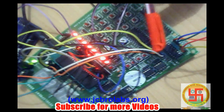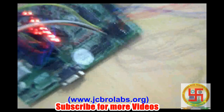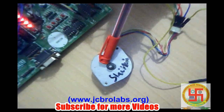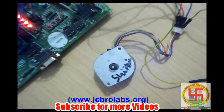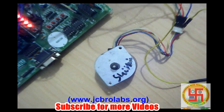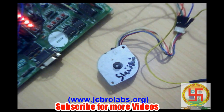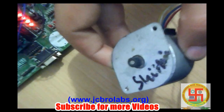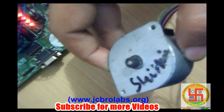These 4 pins of port 1 are connected to the ULN2003 IC, and the 4 output pins of this ULN2003 are further connected to this stepper motor. Right now this stepper motor is running, but due to some arrangement you may not be able to visualize it. The program which we have written is sending this 4-step sequence continuously, so this motor is running like a normal motor. If this can be visualized, yes, it is rotating continuously in full revolution mode.